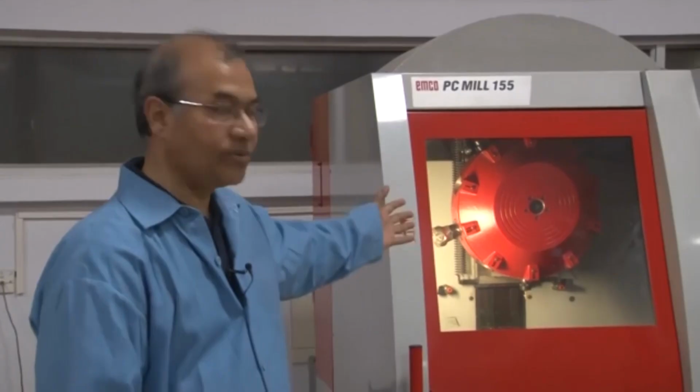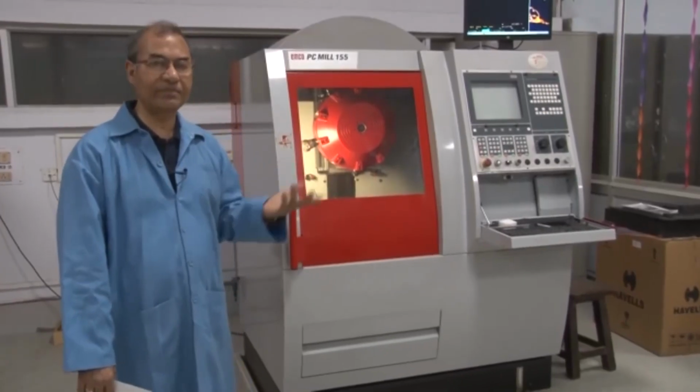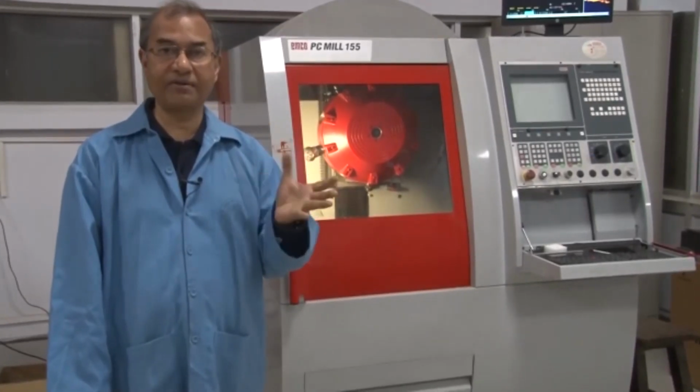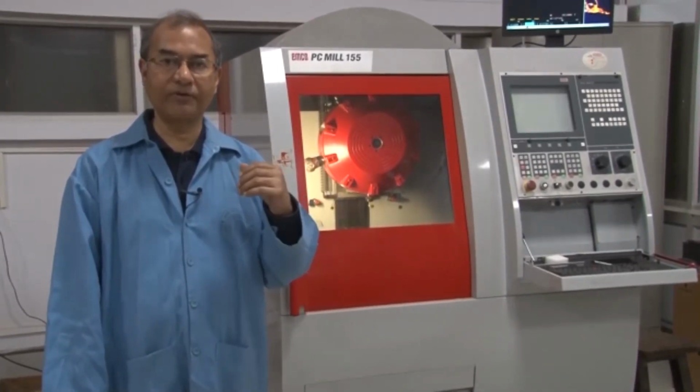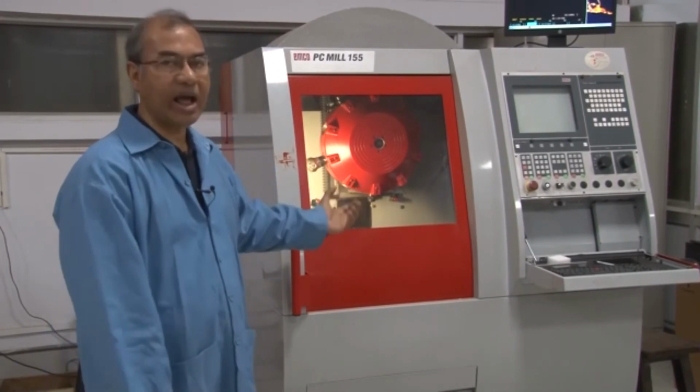That is the one thing. In the conventional machine, what you have seen is the prime drive, one drive, transmitting the power to the output shaft, and the feed is taken from there only. So, there is only one drive for the entire machine. Here in these machines, the power is given to the x, y and z individually, so that these axes can be driven individually. Therefore, any kind of configuration that you want can actually be achieved with a combination of movements along the x, y and z axes.